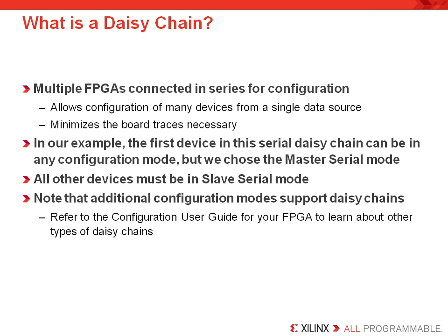But first, we want to recall that the first FPGA in the chain to be configured can be in any configuration mode, unlike other devices in the chain, which must be in the slave mode. You should also note that besides the basic chain we're going to show you on the next slide, other modes support chains. We're just going to start with something basic so you can get a grip on things.